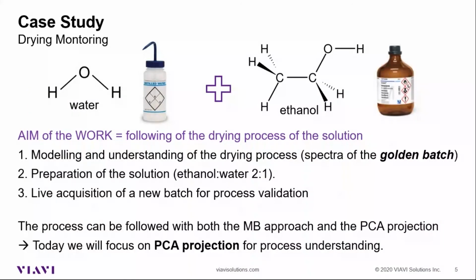And what is the case study? As you know, I'm at home, so I have to create something that I can do with simple tools and with simple stuff that I can buy in the supermarket. So I have some distilled water and some ethanol, and I create a solution that has 2 parts of ethanol and 1 part of water. I already acquired lots of batches to have the golden batch of the drying process. So our idea is that I want to follow the drying process just using the NIR to see what happened to this solution when it is exposed to air.